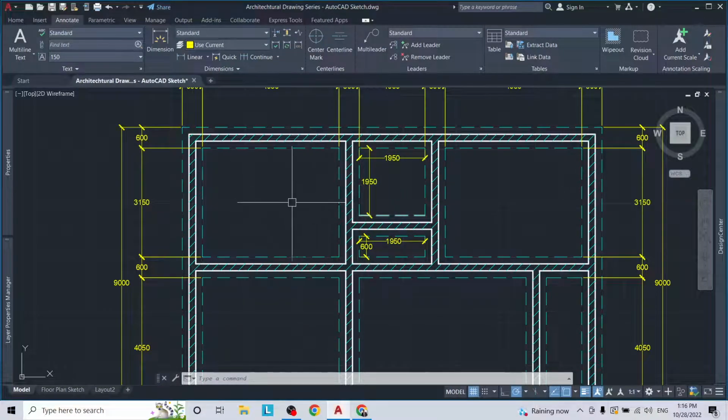So this information now tells the builder where they're going to dig this trench, because these footings are going to be placed in the ground. Dig out the trench, dig out the dirt, then we put the formwork, and then we pour the concrete to create the footing inside of that, obviously with reinforced steel and everything.